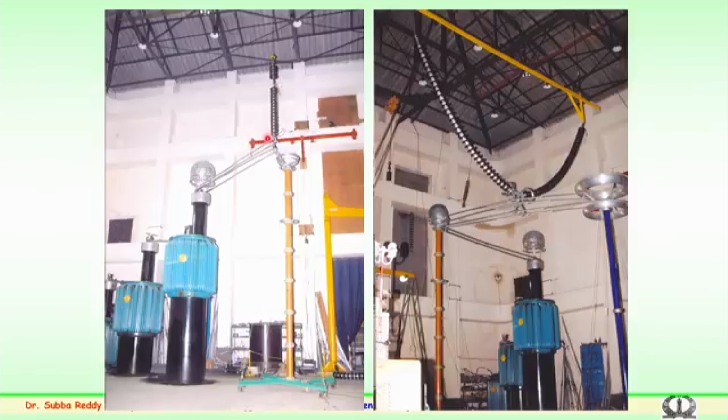This is a suspension insulator string. This is for both RIV and corona. You have a transformer, the filter is here, and from the filter it is connected to the test object, then the coupling capacitor, and through the cable it is connected to the RIV meter. So, this arrangement is again for the RIV measurements for a V type of suspension string. For the voltage distribution, the coupling capacitor and the filter will not be in the circuit.